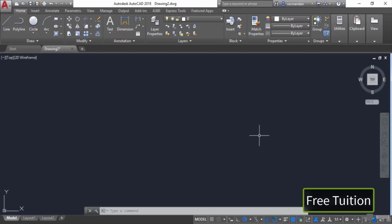So let's say that we want to make a simple line which is inclined to an angle of 30 degrees with a length of 5 units. So there are a couple of methods for doing that as well, but we will use the simple polar coordinate method in this lesson. So let's start the line tool again. Click anywhere in the drawing area, and now as I told you, we need to make a line inclined to an angle of 30 degrees.